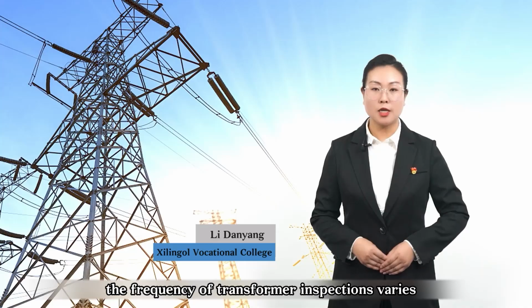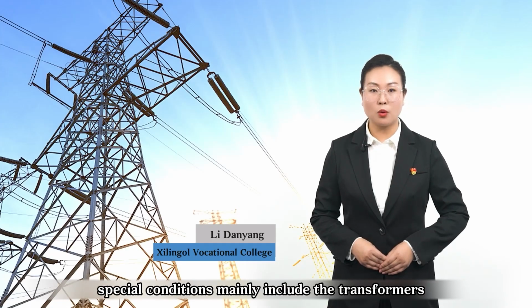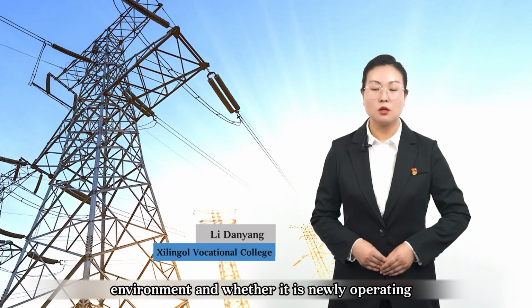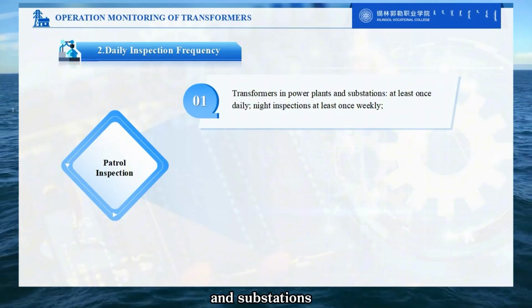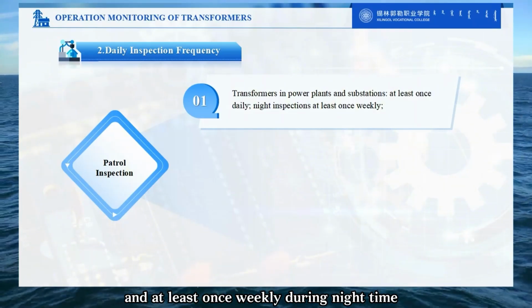Additionally, the frequency of transformer inspections varies. Under abnormal conditions, the number of inspections is generally less than under special conditions. Special conditions mainly include the transformer's environment and whether it is newly operating or carrying a load. First, for daily power transformers. Transformers in power plants and substations should be inspected at least once daily and at least once weekly during nighttime.